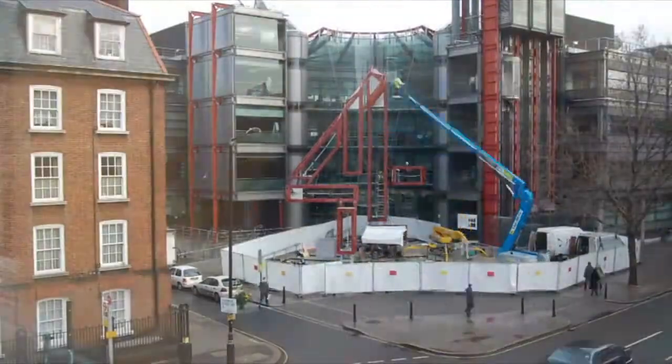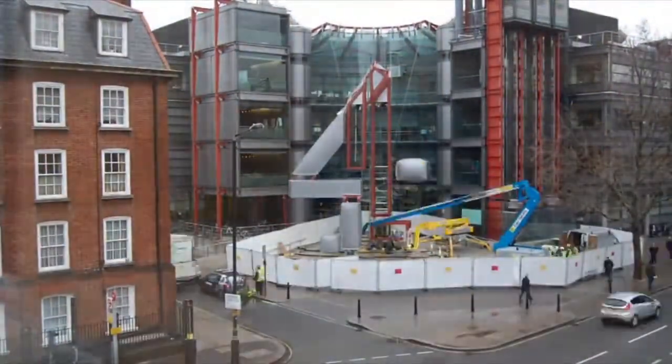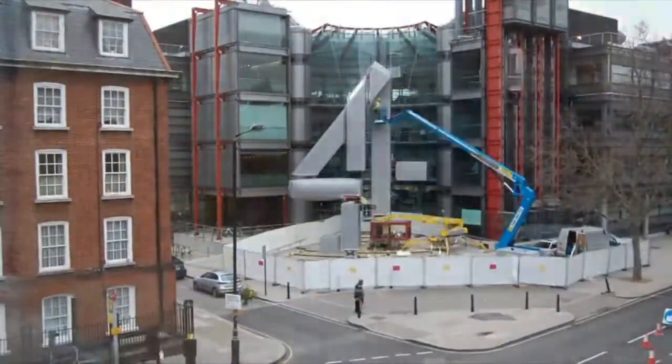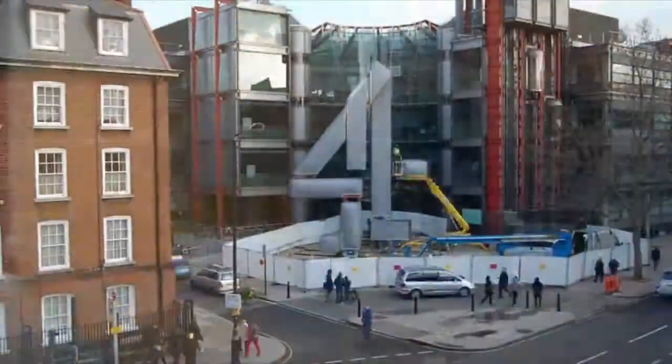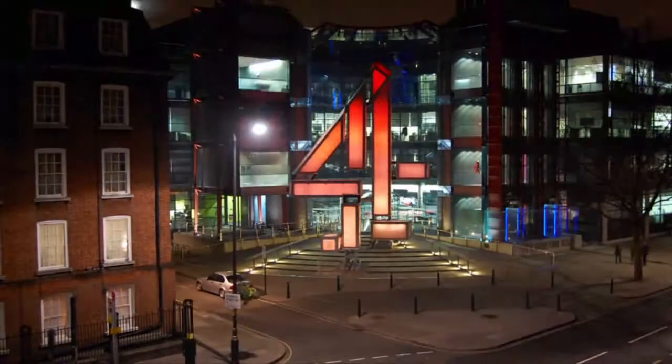As the majority of manufacture occurs off-site, the installation of a tensile fabric structure is fast in comparison to other building materials. Designing and manufacturing tensile structures which are practical for erection is essential. Therefore, components, connections, tolerances, weight and sizes are all considered from the early stage.